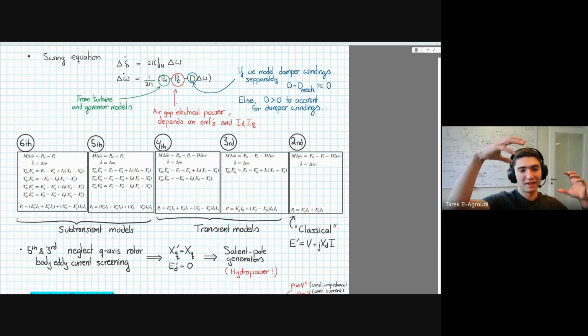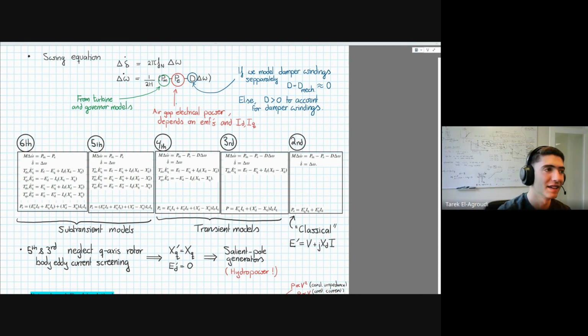At the same time, these 3 phases are connected to the grid. So yeah, I won't go into what 3-phase power is, but AC electrical power is usually transmitted in 3 phases, which are 120 degrees shifted for some reason. But these coils also have current flowing in them from the AC grid. So the stator coils also have some AC current. And this generates an electrical opposing force.